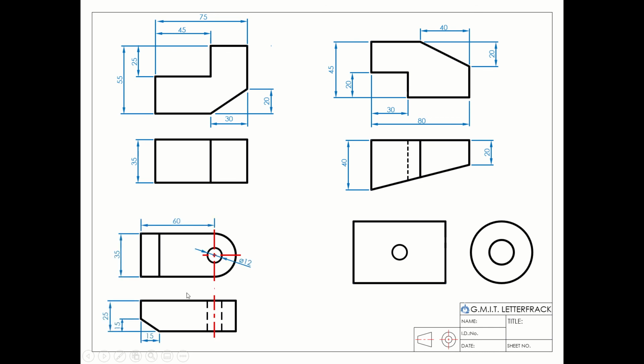And here's our dimensions. So again, our chamfer: where we see the chamfer, we put 15 by 15. We don't need to put the 15 up here. We know that the piece is 25 millimeters wide. We know it's 35 millimeters high. And you can see the hole is given as a diameter 12. Diameter again because that's the 12 mil drill bit that we'll be picking out.